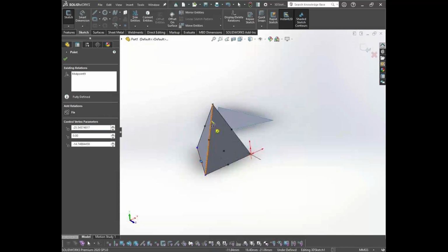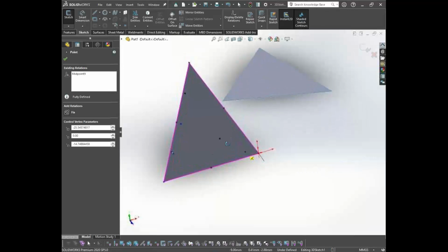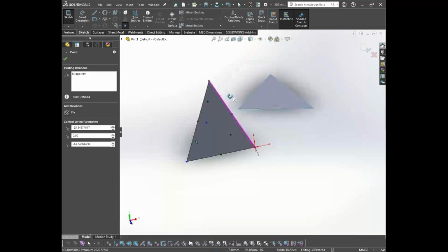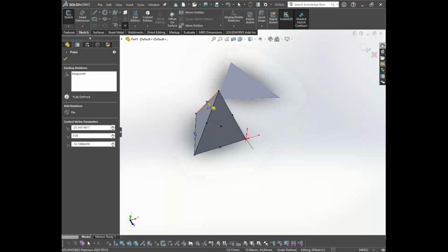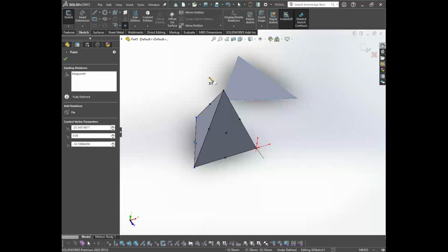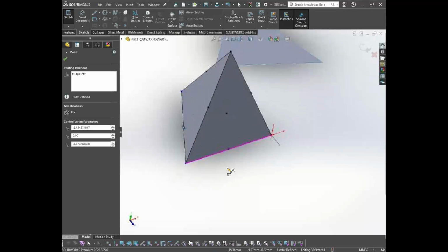So in total now there are 10 nodes introduced in this particular element. What happens whenever I apply a load? I told you that the deformations occur at the node locations. Since it gets one more additional mid node in between, now it will try to deform more accurately after the loading condition that is applied on it.